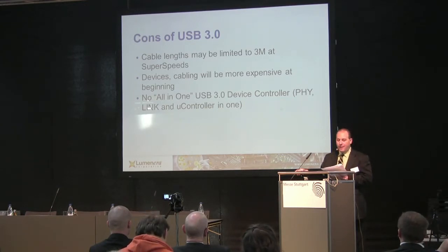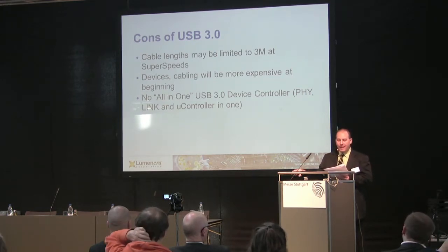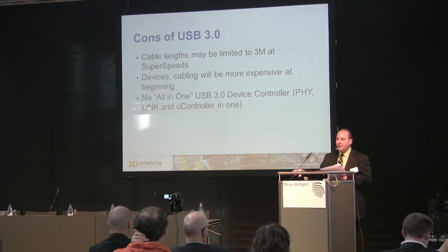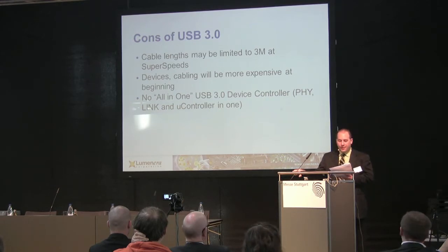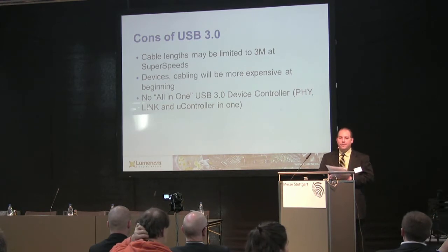For USB device manufacturers, one of the biggest issues right now is that there's no all-in-one device controller available on the market that contains both the PHY and link. USB 3 devices need to use a separate PHY and link controller, which can increase the incompatibility between USB 3 devices as each manufacturer tries to interpret how the specifications should be implemented. I expect that in the near future, more and more USB chip manufacturers will address this issue and come up with a one-chip solution for USB 3. For now, USB devices will tend to be more expensive as chips are needed and IP is required to design and develop new USB 3 products.